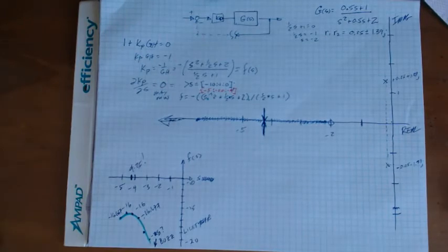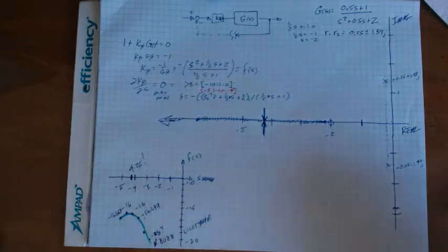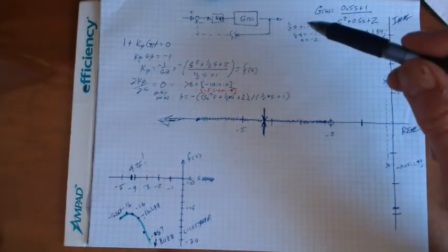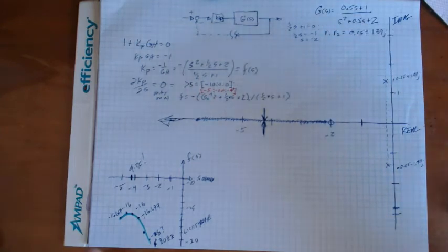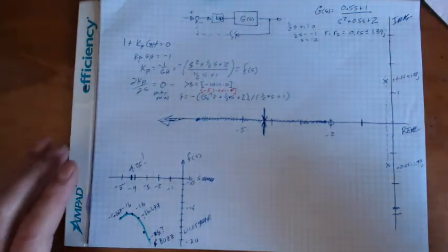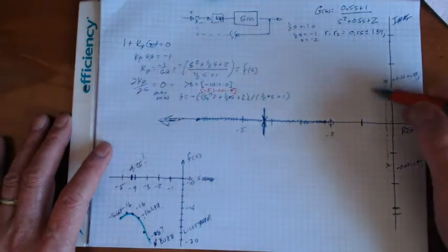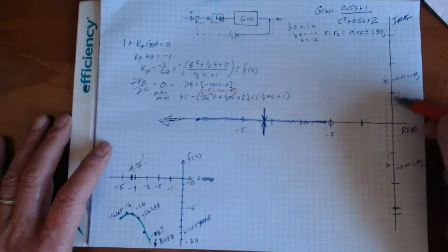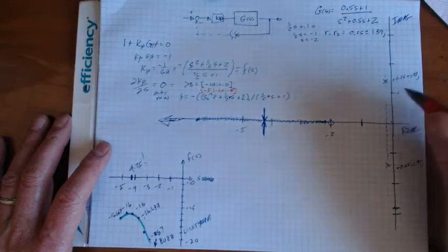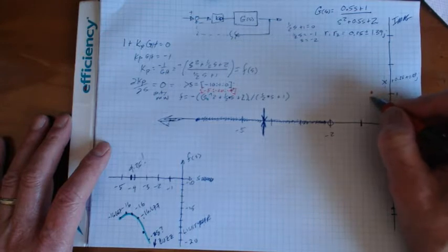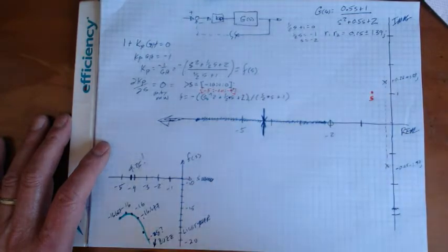to the root locus. Now, what's important here is where do these roots break away? And I don't really know where they break away from, so I'm going to do a little bit of a test situation here. I'm going to zoom in, really zoom in on this. Take a test spot that's really close to this pole. And then I'm just going to make it up. Suppose I choose this is my value S. This is my test location.